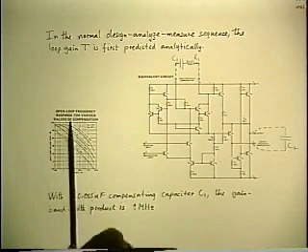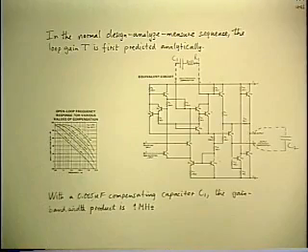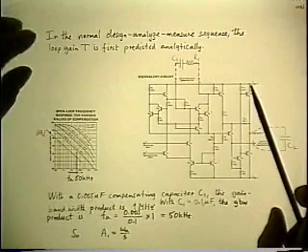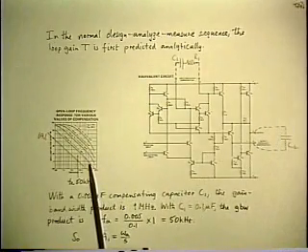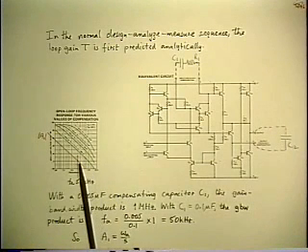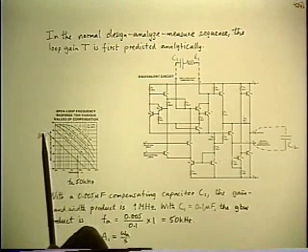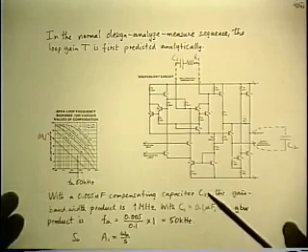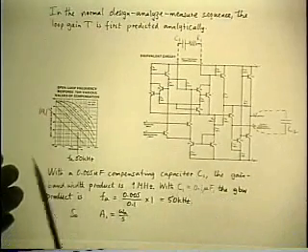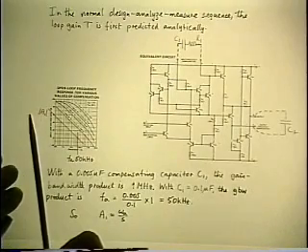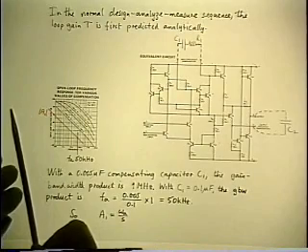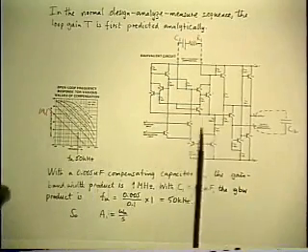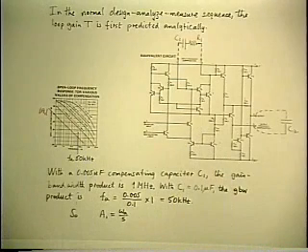But that's okay. If I'm using an even bigger capacitor, all I have to do is scale it down by the factor of 20, and that will change the unity gain frequency from 1 megahertz down to 50 kilohertz. And the pole at low frequencies is moved even further off, but according to the same argument that we've talked about several times, I don't even care where that is. I don't care about the fact that the zero frequency gain will be finite. I'm not interested in it. The only important part of it from the point of view of the loop properties is what happens around crossover.